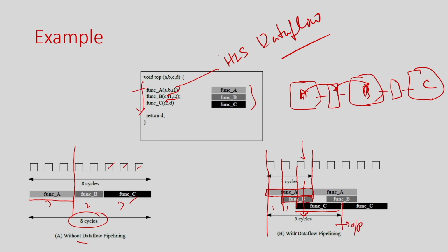So, the throughput becomes every 5th cycle here, whereas there the throughput is every 8th cycle, right. So, the next output will come after 8 more cycles. In the non-dataflow version of the hardware, the throughput will be 8, right, 1 in 8 cycles, and here it is 1 in 5 cycles. Most importantly, since function 1 completes its execution here,